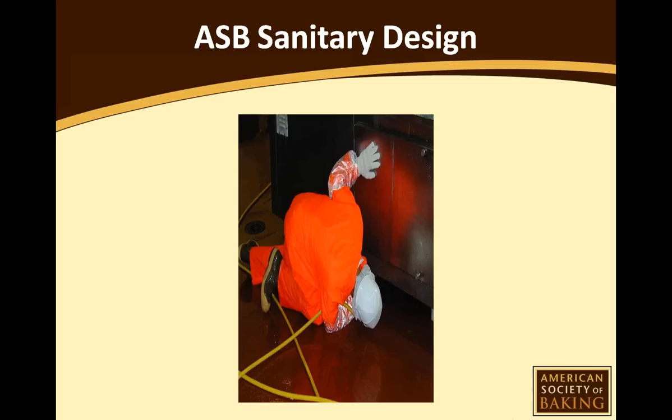And this picture tells a lot of stories, and oftentimes I've used as a caption, hey, look what I found, a floor drain. It may not be uncommon to have a floor drain stuck underneath a piece of equipment, but this picture captures the essence of what we do not want to happen. Readily accessible is a location that can be safely reached by an employee from the floor or platform or a permanent work area. And obviously here you can see a very close proximity to the floor.